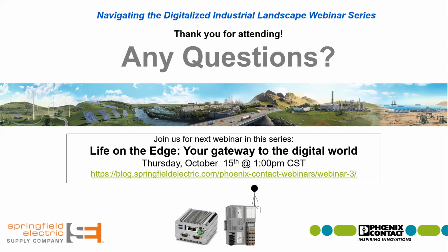Yep, that's okay. I mean, you need a NAT router per PLC. It depends on how your network is set up. If they're all connected locally, you can't have the same IP address. Otherwise, you're going to run into conflicts. But if you have a NAT router or a NAT switch there, you could do some local NATing. But per PLC, one NAT router for each PLC, that'd be a good way to segment your network.